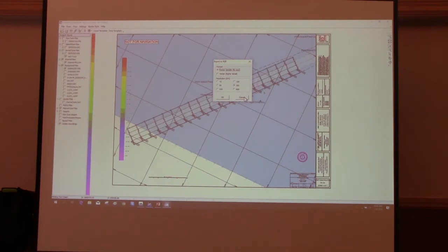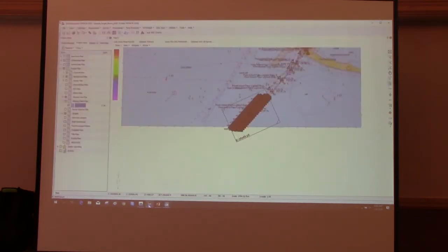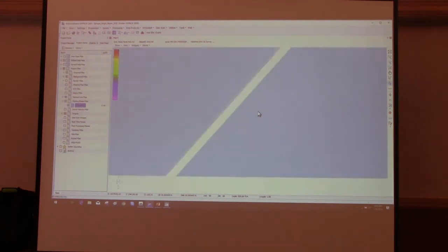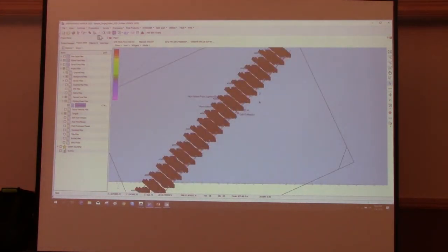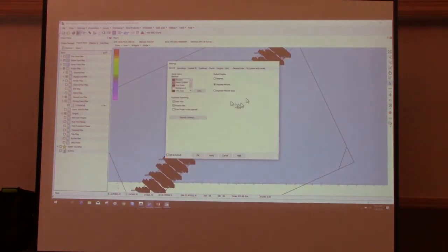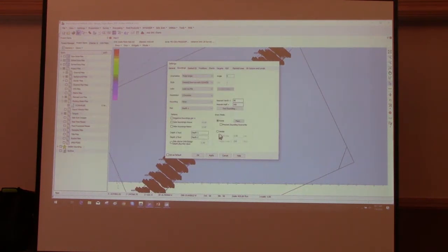Well, legible. Yeah, it's interesting you say that, because in HYPACK you have the same options in the shell for the soundings. If you go to the soundings tab, choose the vector option here and use the standard vector size, and you play around with the scale here, you can see whether or not they're actually going to overlap.